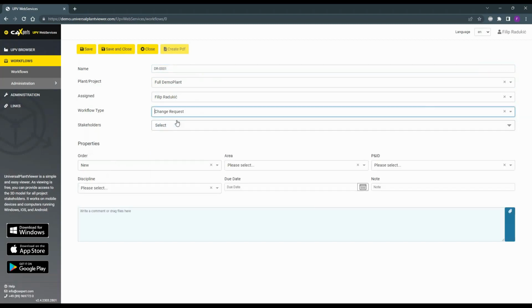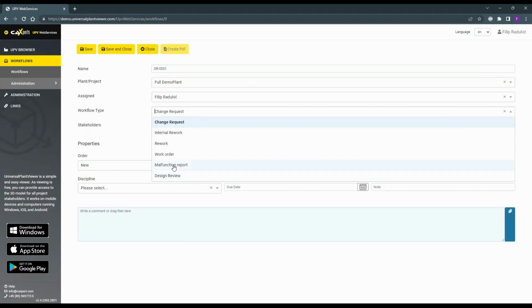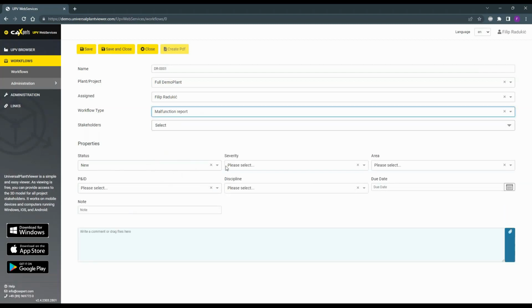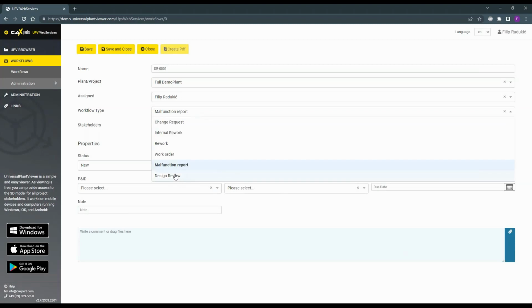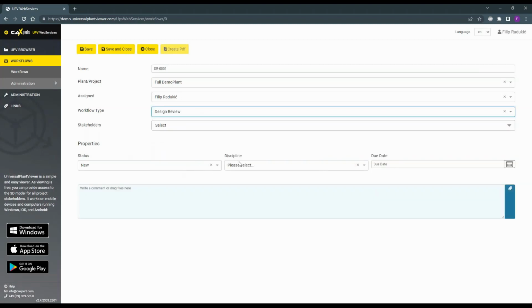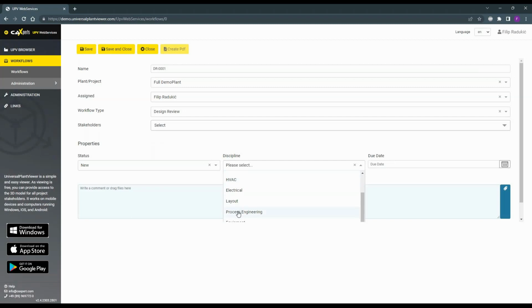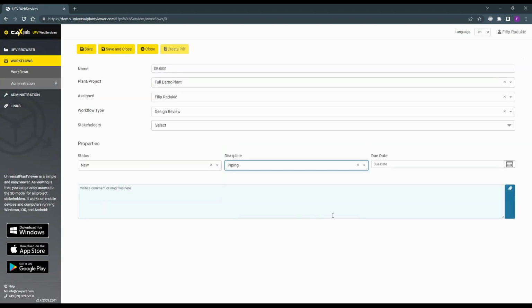So you see, I have here order, area, PNID, discipline, due date, and note for change request, but for malfunction report, I have status, severity, area, PNID, and discipline. For design review, I'll just have a status and discipline. So I'll pick piping again and save.